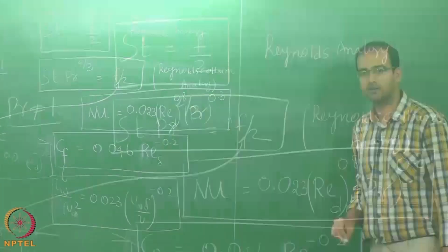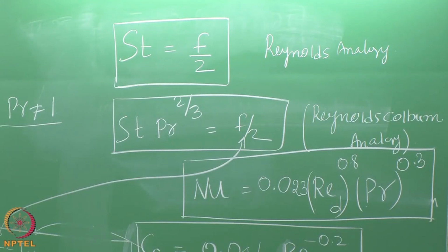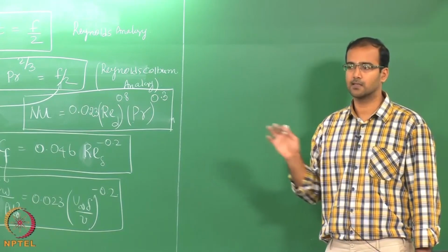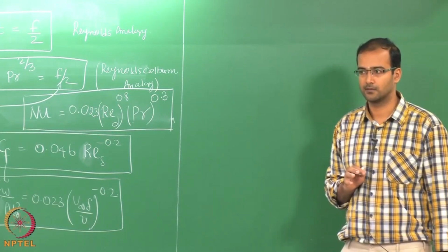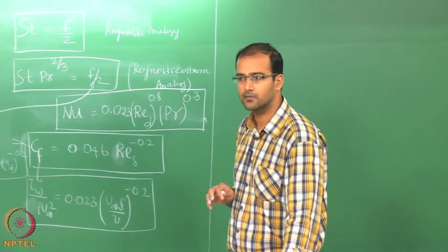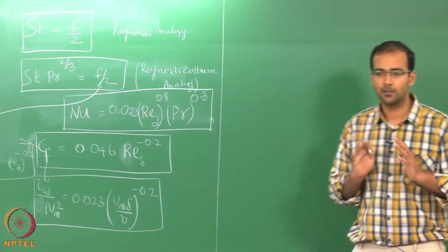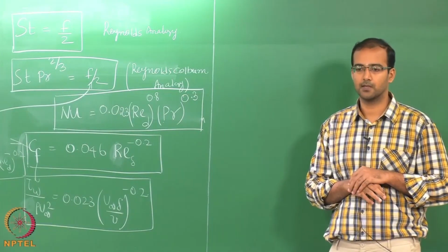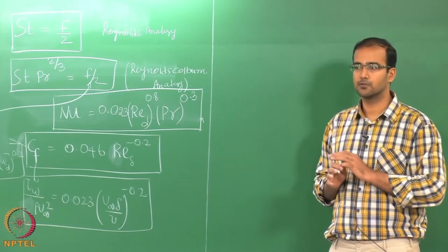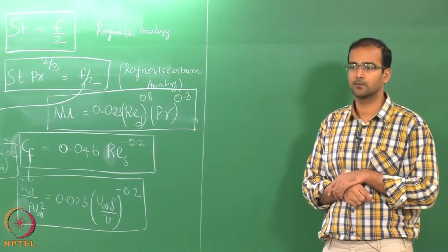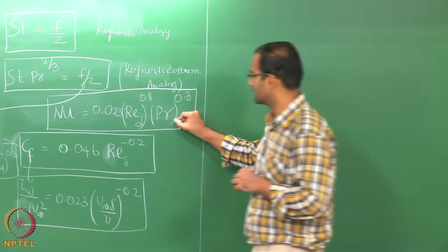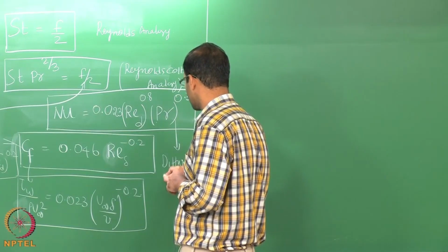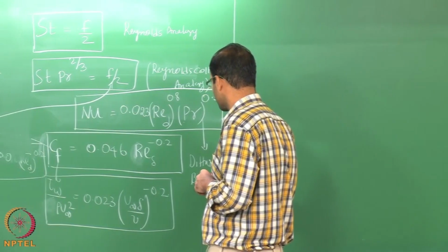This is therefore a correlation for the Nusselt number directly derived from the analogy. We are not solving the energy integral or anything here. This correlation gives you a very simple approach directly from the analogy. You know the expression for the wall shear stress, therefore we use the analogy and directly get the expression for the Nusselt number. This correlation is popularly referred to as the Dittus-Boelter equation.